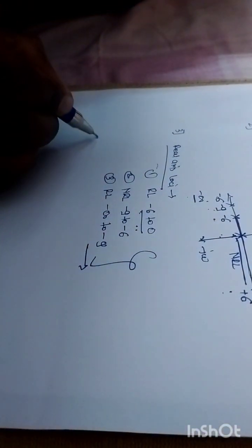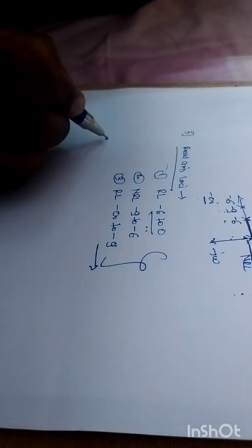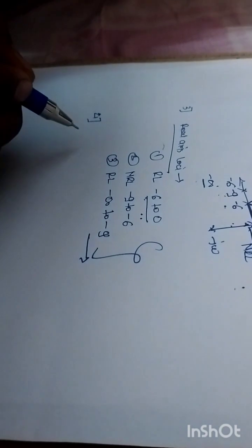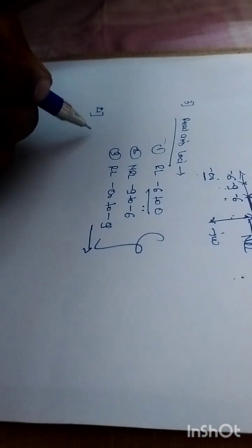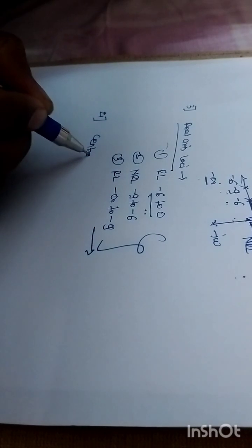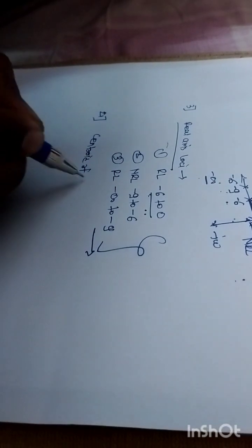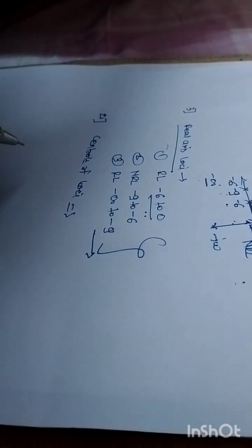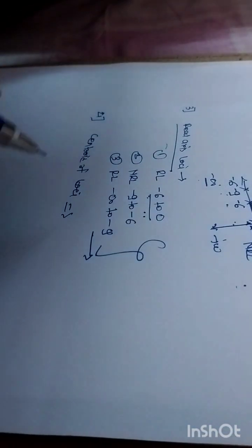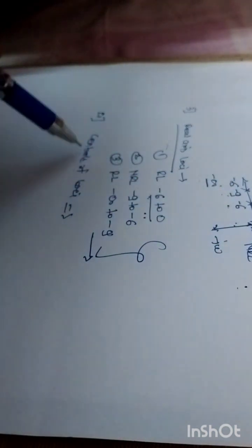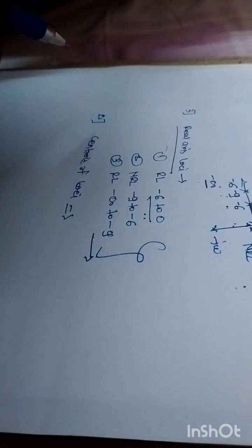Then immediately after that we will go through the design step number 4. The design step number 4 is nothing but what? How to tabulate the centroid of loci. This is the step number 4, right? Centroid, in the sense, we need to determine the intersection point on the real axis, that is nothing but the centroid of this loci, right?